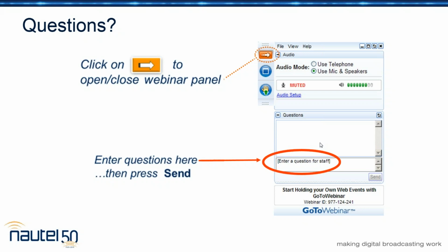MPX over AES is wonderful for SFNs. It's also wonderful because it gives you the opportunity to have your digital audio processor have a digital audio output and go straight into the exciter of the transmitter, which is digital, and you lose no audio quality. You go through no A to D or D to A, and you don't lose audio performance.